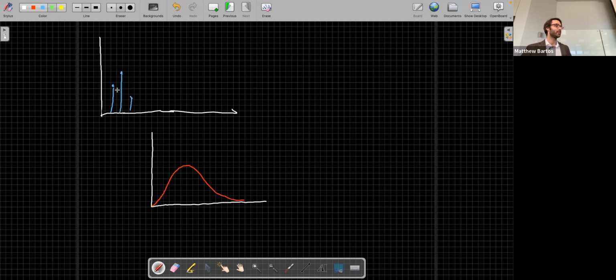We take this part of the rainfall event, scale our unit hydrograph by this component and add it on top. Then finally, we take this component here, scale our unit hydrograph by it and add it on top, and we'll end up with a smaller part that's added on, shifted slightly to the right because it occurs later on. So this is conceptually what's going to happen.